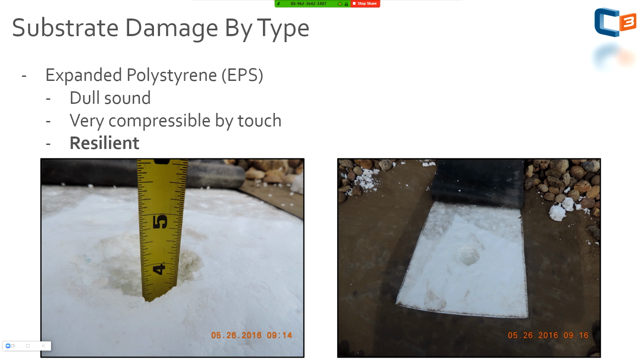So something about this, and I didn't really discuss this earlier, but ISO is closed cell foam. So that means that water does not absorb into the product. There's not open cells between all the insulation components where water can fill those voids. With expanded polystyrene, it's a little different and a little trickier because if you look at polystyrene or styrofoam, you'll see that there's little beads, and those beads are closed cell. But when they compress all this together, it'll leave little voids between those beads. So part of this is open cell, but it's considered a closed cell product. But just know there's a certain amount of water absorption that can occur with these.